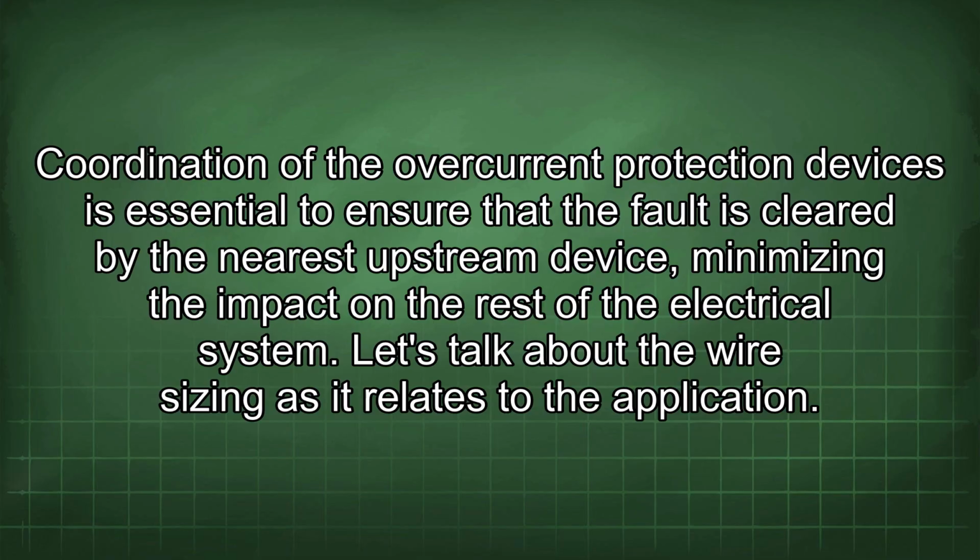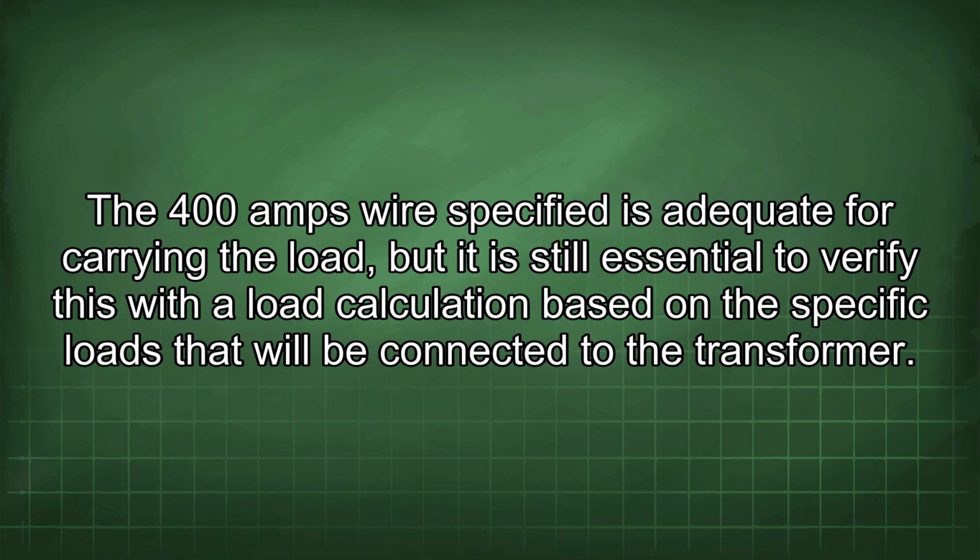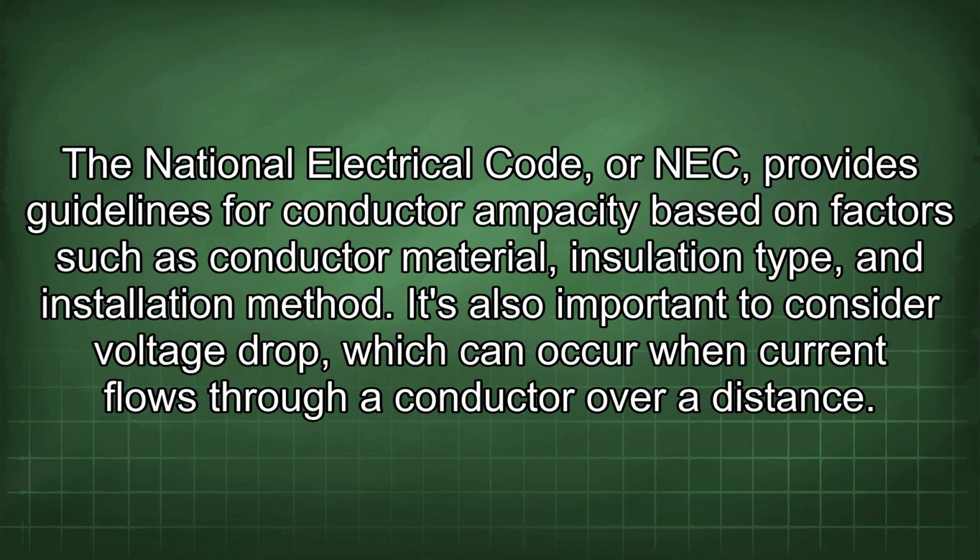Let's talk about the wire sizing as it relates to the application. The 400 amps wire specified is adequate for carrying the load, but it is still essential to verify this with a load calculation based on the specific loads that will be connected to the transformer. The National Electrical Code, or NEC, provides guidelines for conductor ampacity based on factors such as conductor material, insulation type,